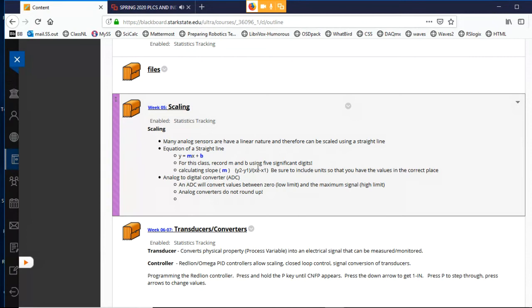If you don't have anything on your load cell, you would expect it to be reading 0, and yet those load cells read some pretty high values even when you don't have anything plugged into them. So it's critical that you go through the scaling process.